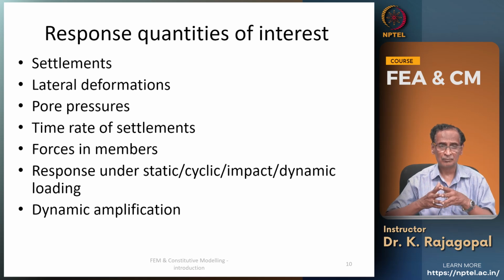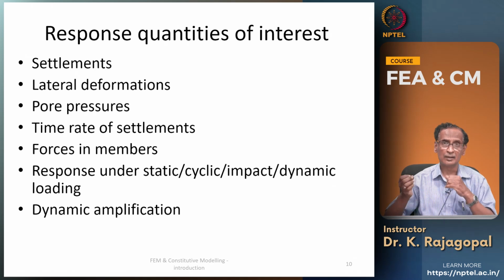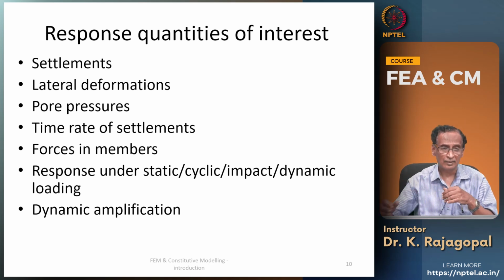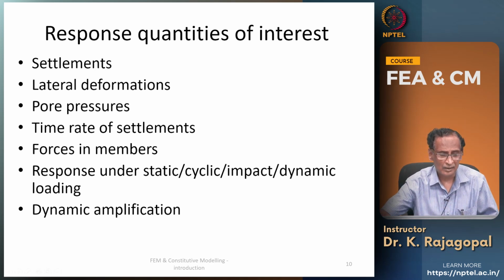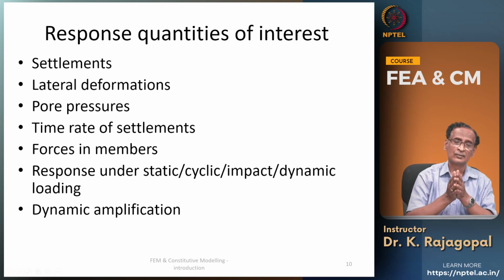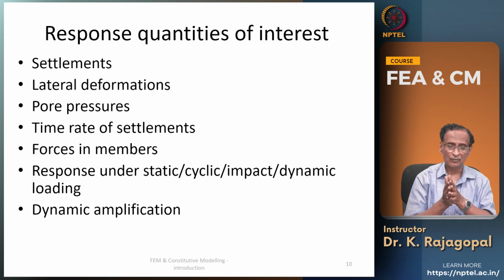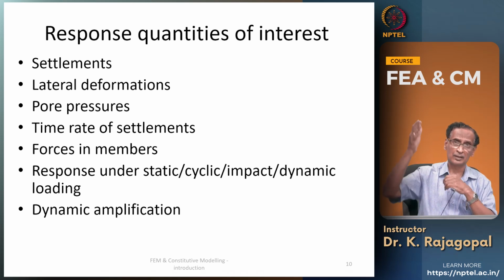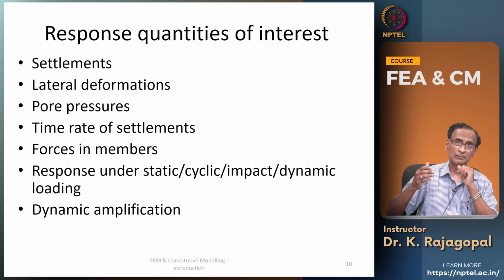Then what are the different responses that we are interested in determining through this analysis? Obviously, the first thing is we would like to know, if you construct, what will be the settlement, both total and differential. Then what could be the lateral deformations, especially if you are making any deep excavation?